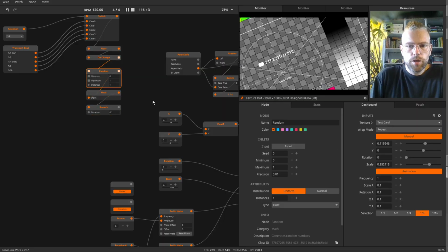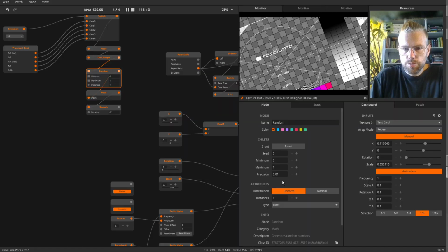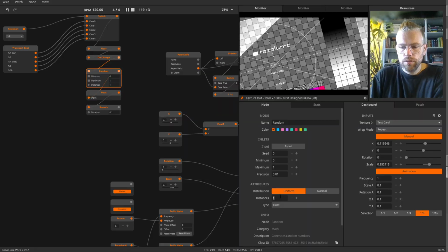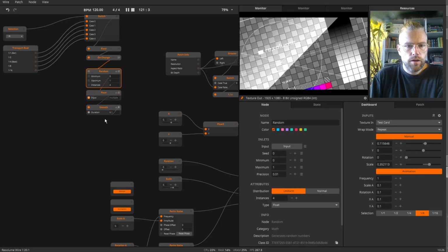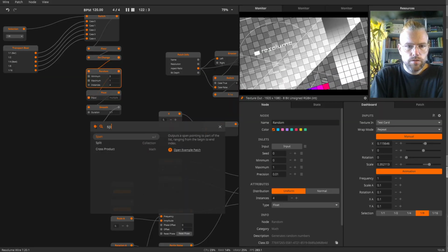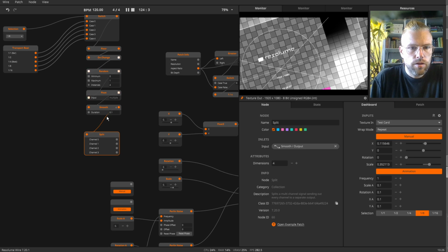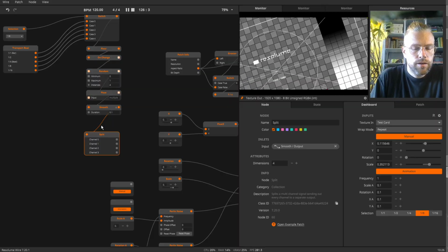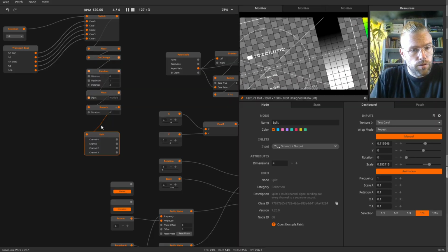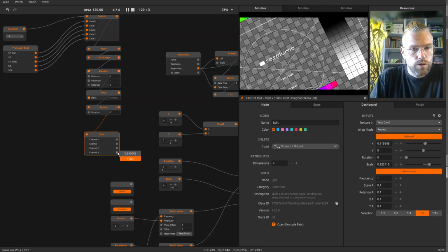And I think we want to have 4 because we have 4 parameters we want to animate. So we can choose our instances here and say 4. And we say split. This dotted line indicates that we have 4 data instances running through this wire, and you can split them to get all your different values out of there.